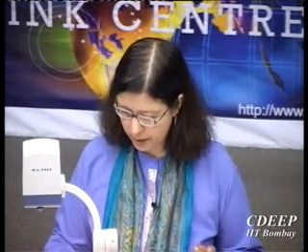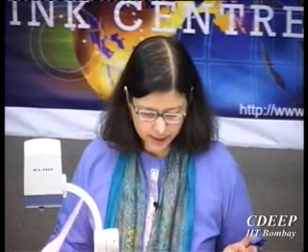Okay, so then what we did, we just had a small discussion about sensitivity and then practically how we should choose topologies as per what we want. But the moral is the transition band is very difficult to control, and it always affects the performance of the filter with respect to process variation, because group delay also is sensitive in this region. And then how to do frequency transformation, and then what is the corresponding multiple feedback realization similar to ladder, and then we had an example for that.